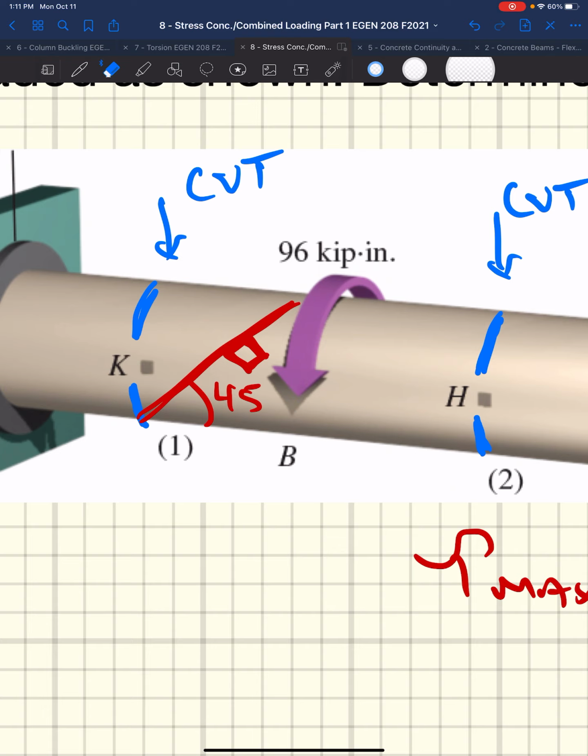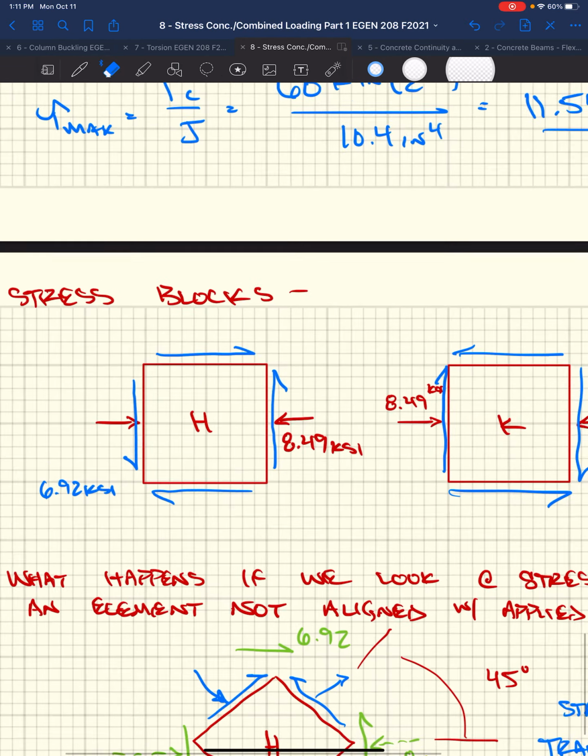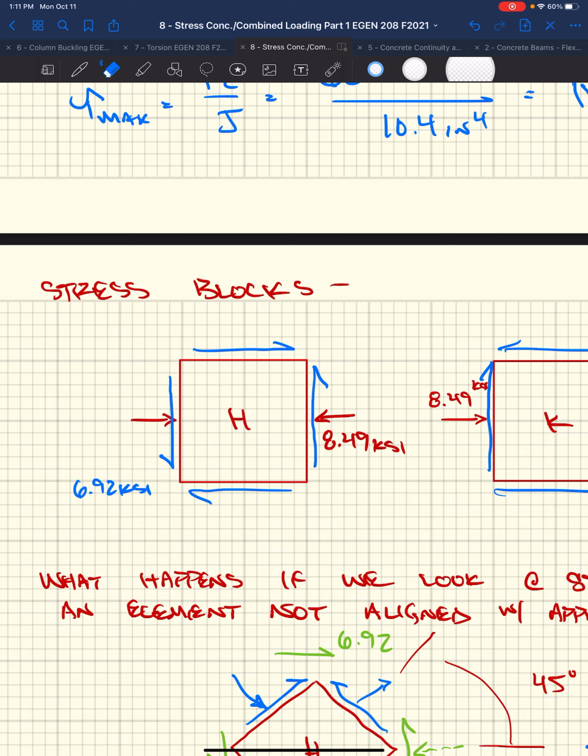And we talked about equilibrium, which we will talk about again here shortly. That essentially results in this shear stress acting, right, equal and opposite on all four faces in order to keep this thing from twisting, right, spinning into space. So to maintain equilibrium, they look like this. So we got our two stress states.